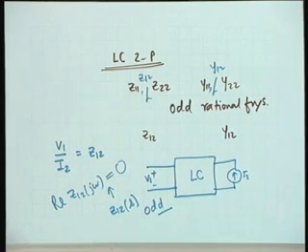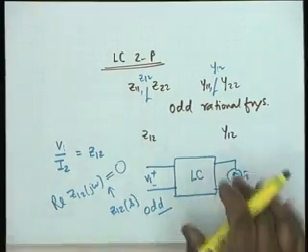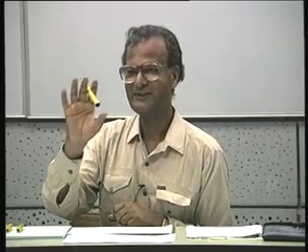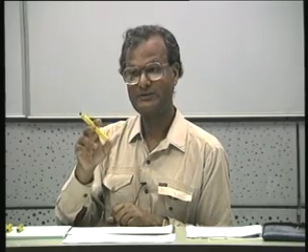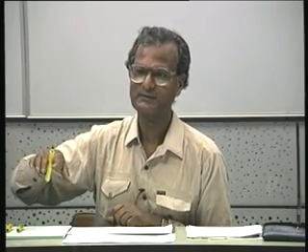We cannot have a real part. Isn't it obvious? Since it's an LC, it is not a driving point function. If it is a driving point function, it is obvious. It is a transfer parameter now, which means that at any point you measure the voltage and at any other point you measure the current, these two must be 90° out of phase. It cannot be anything otherwise. They cannot be in between because it is an LC network.